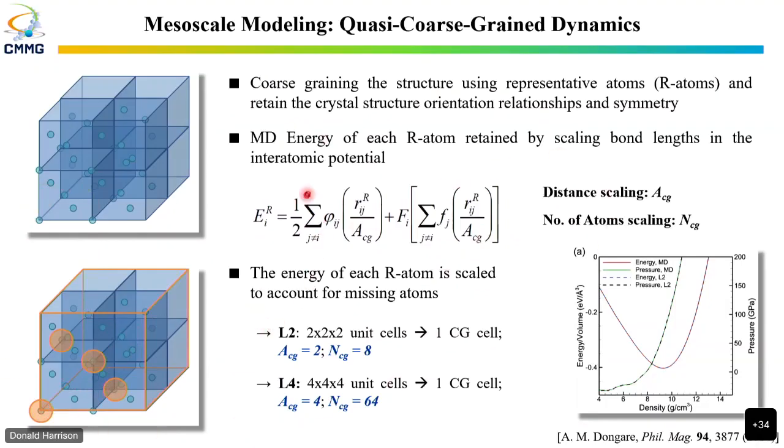So we normalize it by the level of coarsening, and we can reproduce the equation of state of the system. We can reproduce all the phase energetics as well. The defects is a slightly different thing. It will still nucleate defects, but the nucleation energy for defects is a collective nucleation energy for many defects. So you're looking at this methodology where you can have dislocations that are generated in the coarse grain system, but each dislocation basically means that the system has had enough time to nucleate many dislocations by that time.